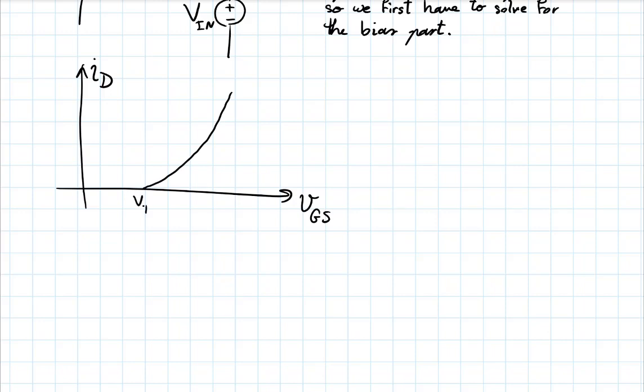If this is VT. Now, what the question is, well, if we were here, if this was my bias point, VGS, if I made any change around here to the voltage, it would correspond to this change on the current axis, right? And I am approximating this with a straight line. This is my approximate linear response, right? And of course, I've exaggerated things here so that we can see. That's the domain we are covering on the current axis with that.